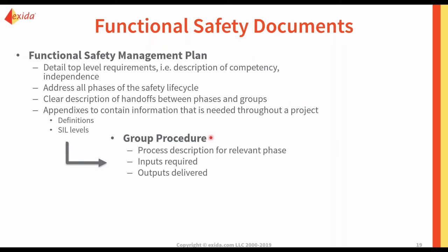And so then the process would say, based on this information, perform a SIL verification using Markov modeling, document what accepted sources of failure rates are, what typical assumptions are made, and really ensure that when going through and doing that SIL verification you're following the robust procedure.